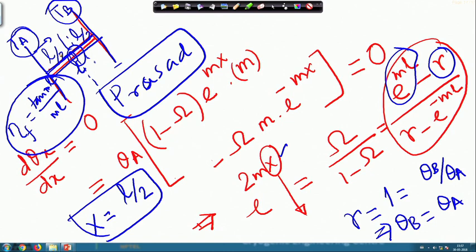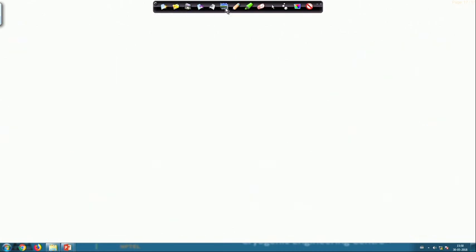But as we have said, this corresponds to a particular situation where half of this fin is attached to this plate, or half fin idealization as it is called. It is possible only when TA and TB are equal, but in reality there are several situations where TA is not equal to TB, and in those cases we have to go for a different approach. How do we estimate? One way is that we try to find out exactly where that extremum is located.